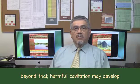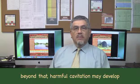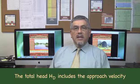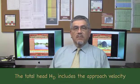Beyond that, harmful cavitation may develop. The design head H sub D excludes the approach velocity. The total head H sub capital D includes the approach velocity. The spillway rating is based on the theoretical broad-crested weir equation, which assumes critical flow in the vicinity of the weir crest.